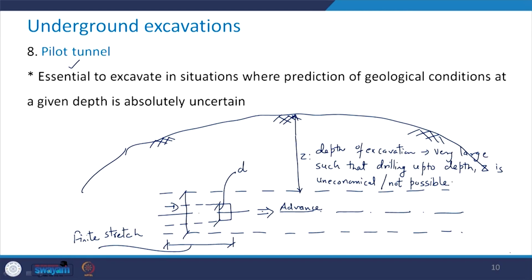So, in that case we need to go for this pilot tunnel excavation having a diameter smaller than the diameter of the main tunnel. Obviously, this will be done for the finite stretch, and once this pilot tunnel is excavated, then one can get the idea about the geological conditions which are exposed at these surfaces of this pilot tunnel.